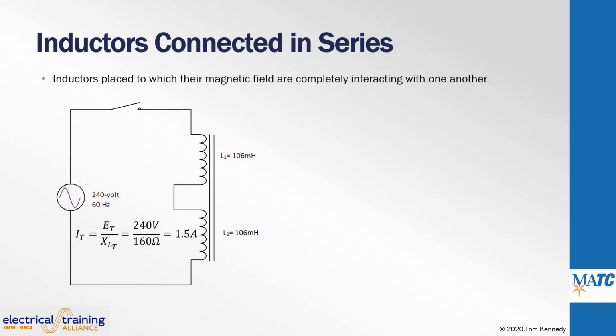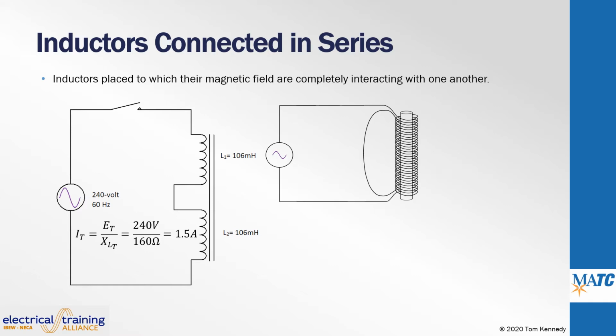For this next example, the inductors shown connected in series in the schematic are placed so that 100% of the magnetic fields are inductively coupled with each other. The coils are placed so the magnetic field produced by each coil is in the same direction. The lines of flux interacting between the two coils will cause additional counter-EMF to be created.